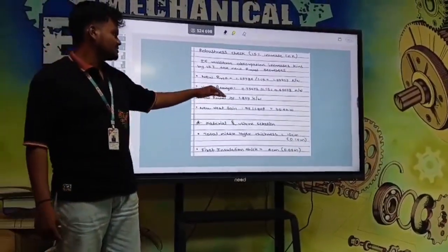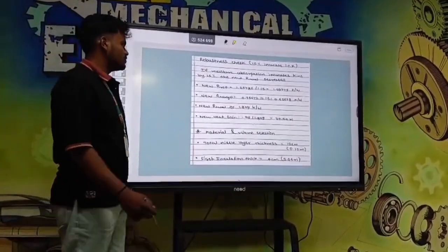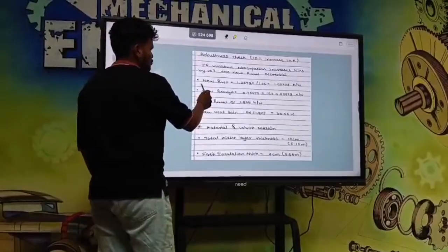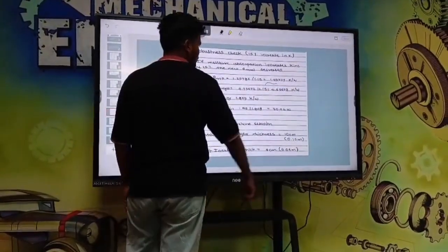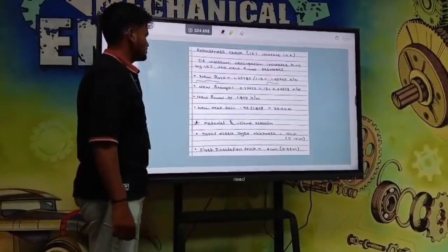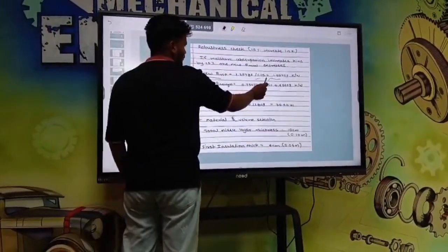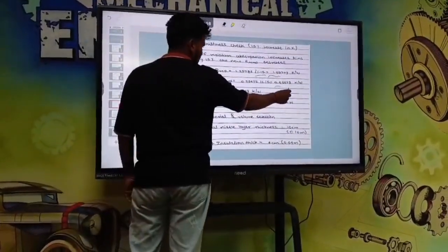If moisture absorption increases K of the insulation by 15%, I have calculated the new total resistance and the resistance for each layer. For the VIP layer, the new resistance is 1.09, and I calculated again by dividing, getting 1.15. The new total resistance of each layer is shown here.